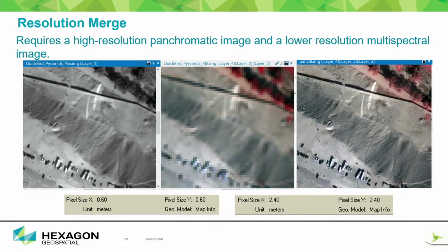You can see and you can analyze these two types of imagery. You can see that in the panchromatic band there is a vehicle, clearly visible here, clearly identifiable in this image. But here you can see some vehicle is there also, but are you able to identify this? No, because the resolution is 2.40 and here the pixel size is 0.60, so whatever information is less than 2.4 meter has mixed pixels, basically, so the information has been merged.